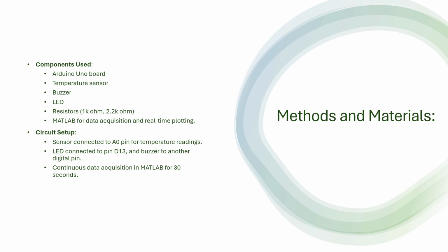To achieve our objectives, we used an Arduino board, a temperature sensor, a buzzer, and LED resistors, and MATLAB for data acquisition and plotting. The temperature sensor provided continuous readings, and we programmed the Arduino to trigger the buzzer and LED when the temperature crossed the threshold. The system was designed to run for at least 30 seconds continuously, monitoring the temperature while MATLAB plotted the data in real time.